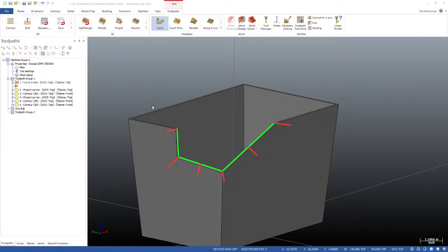So the first thing I'm going to do is either select a tool or create a tool. Let's go into the library. And I'll go to my tool filter, and I'm going to use a sharp corner flat end mill. So I'm going to double click on flat end mill so that it will automatically grab all my flat end mills. And then let's grab a 3/8 bit. So I'll grab my 3/8 flat. It comes in as tool 287.